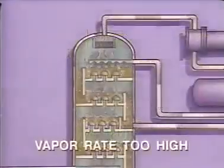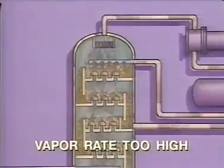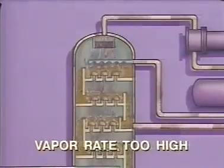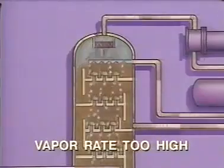A vapor rate that is too high can also cause flooding. The pressure from excessive vapor rates resists the flow of liquid down the tower. If this pressure is high enough, liquid will back up the tower and flooding occurs.